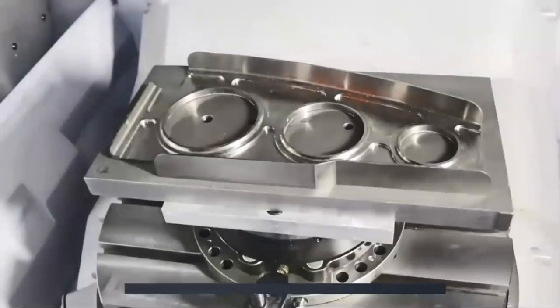After creating the probe path, you need to simulate it and generate the NC file. After generating the NC file and running it on the machine, the machine will generate an NC code itself. Okay, and that NC code is to be transferred to the operator who is using your PowerInspect software. So that may be a DAT file or any kind of file format received from the machine. So let's see.